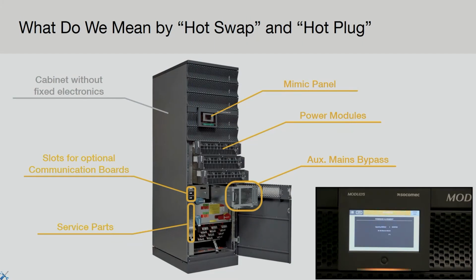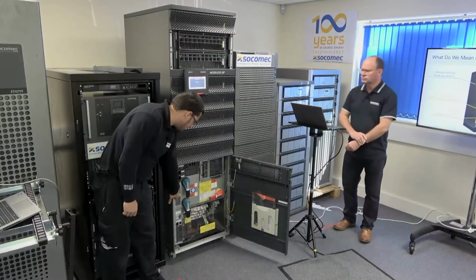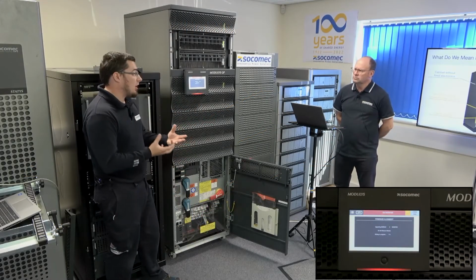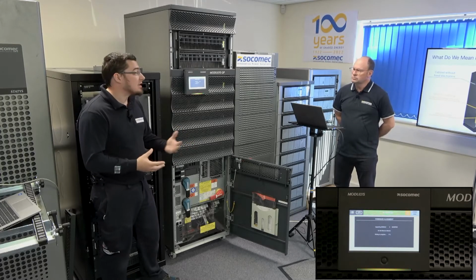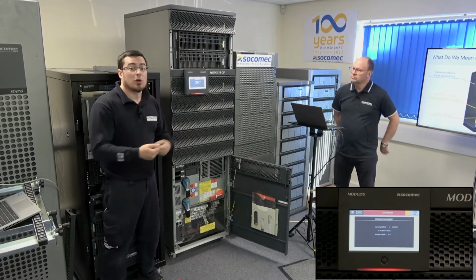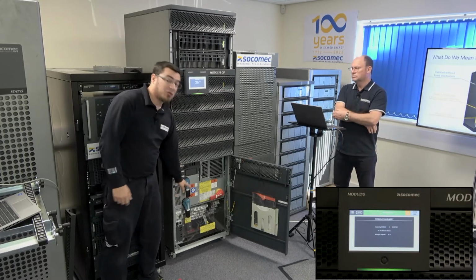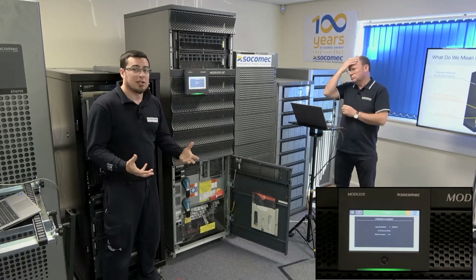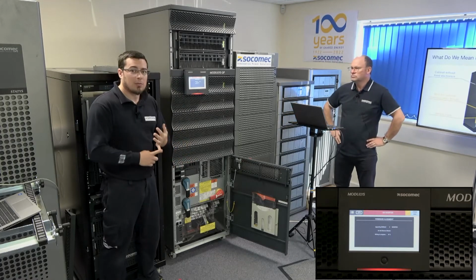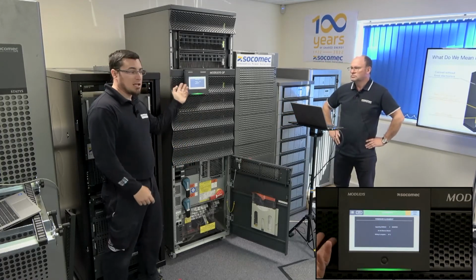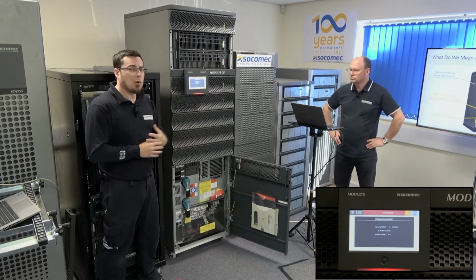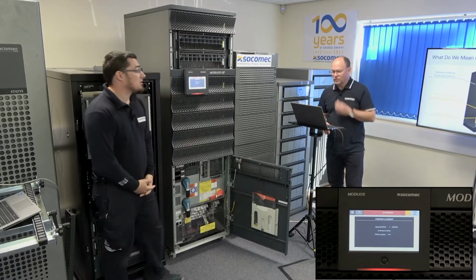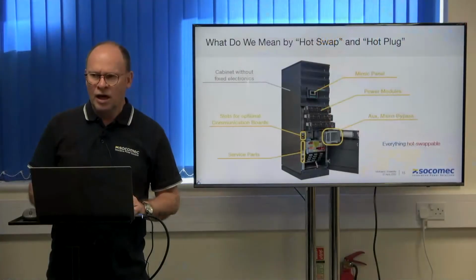Yeah, so I mentioned earlier we've got power supplies, but if you can just about see, there are two power supplies with the system, and they are redundant. So even if you come to replace them after, say, 10 years, you can do them independently, you could change one at a time. In fact, you could pull all the power supply fuses out, and as I mentioned, the software built into the system carries on running, it doesn't matter. So we can do a controller replacement, power supply replacement, the display, and absolutely everything can be done whilst the system's still on inverter and your load is protected. So it's really good. Good, okay.